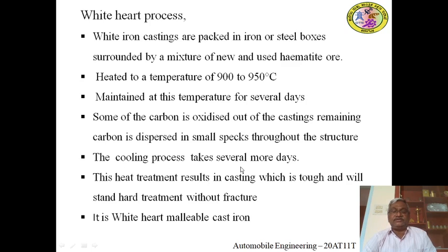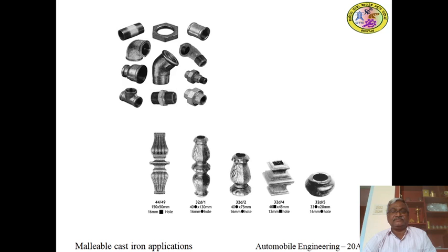The cooling process takes several more days. It is allowed to cool for several days. This heat treatment results in a casting which is tough and will stand hard treatment without fracture. This malleable cast iron is called white heart malleable cast iron because of its white color.